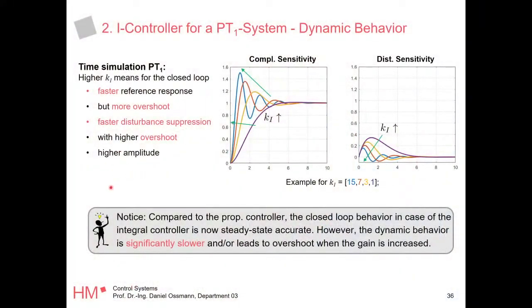Now you could think of a solution. What would be accurate and fast? It's actually pretty simple. Okay, so the key takeaway here, your integral element makes your proportional system accurate.